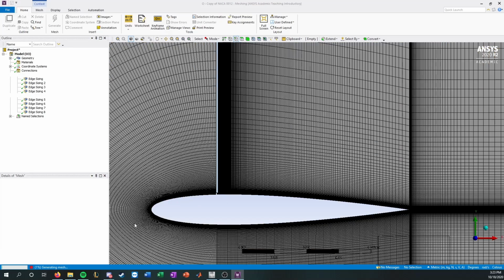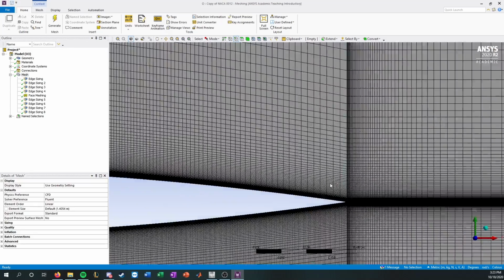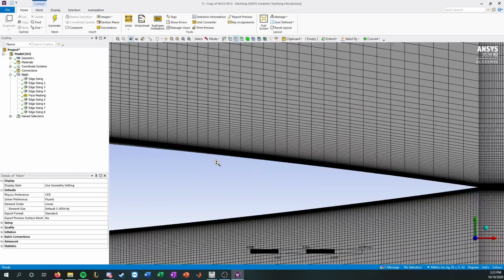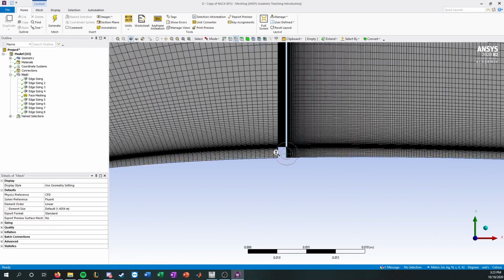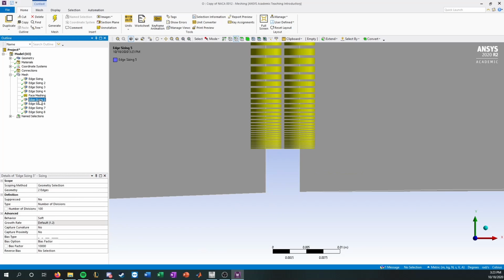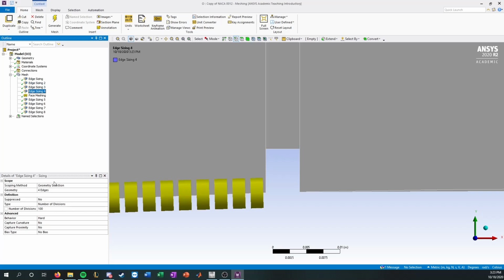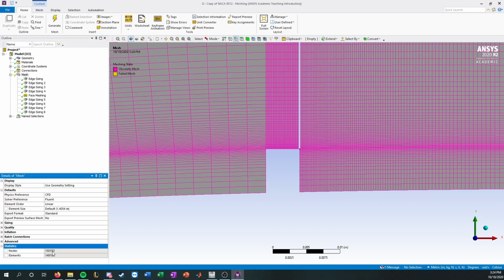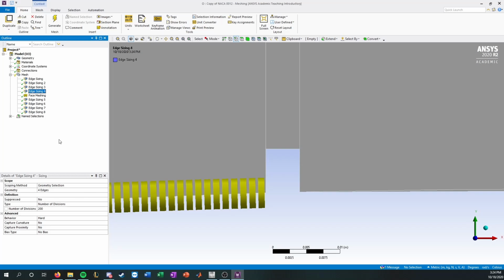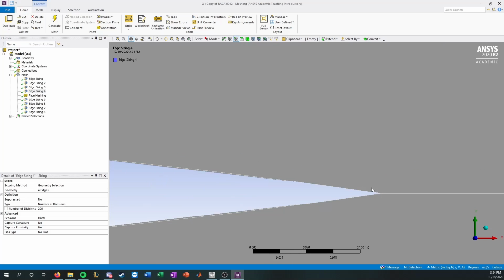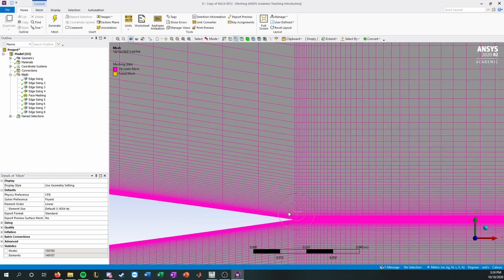Boom. Looking like it's going much quicker, and there we go. Another issue I see here is this is a change in volume that's pretty steep, and sometimes you may not want that steep of a volume change. But this definition looks good because this is where the vortexes are going to be created. So let's look at how much computational resources I'm using right now. 150, not bad, so I'm going to double this to about 200, get more definition up here. I could try to get more definition on this backside because this is a little bit worrying.